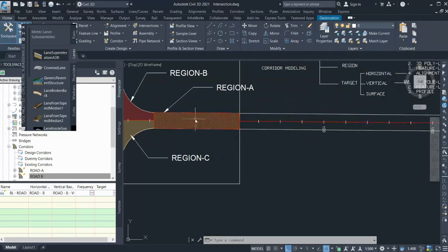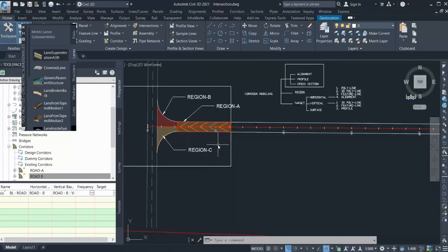And if you have any kink, there will be some problem with the targeting or level. So you always create a contour for your corridor to see that everything is right. Here the contour looks perfect. Now the next thing is to create the corridor with the offset assembly and curve return.